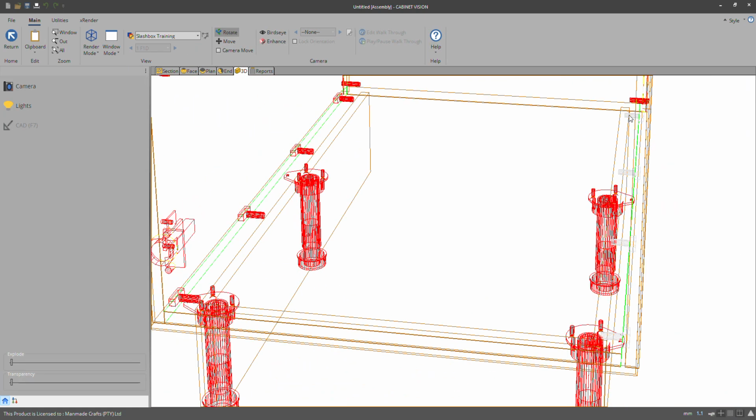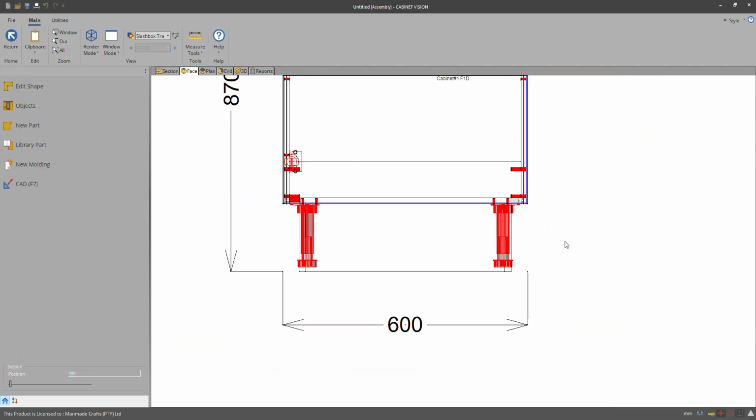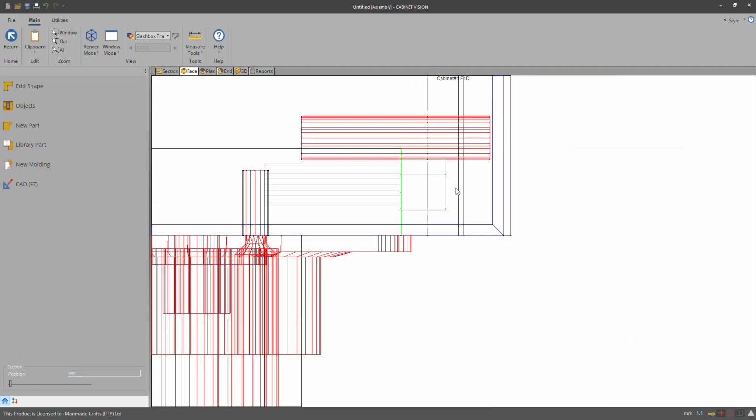See what happened then? My parts went into gray because there's a gap. The connection isn't touching the next part. So if something like that happens, the gap can be a millimeter. If the connection isn't set up for that millimeter variance, it will not fire. The parts need to connect. Otherwise, the connection won't fire.